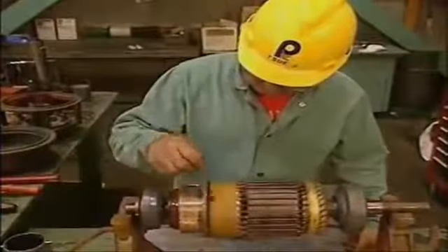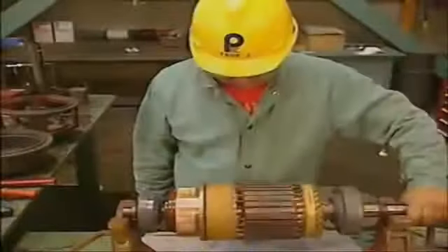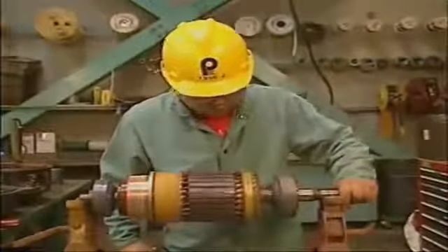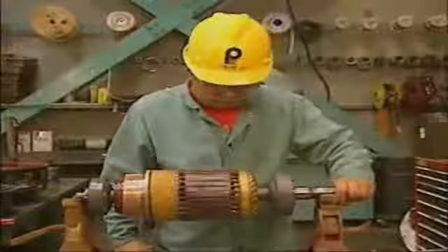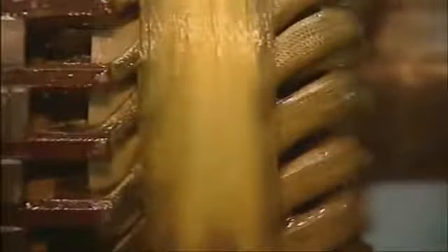The area behind the risers should be checked to make sure that there is no melted solder, dirt, or carbon dust there. If any foreign particles are found, they should be removed with an approved cleaning solvent, rags, and a vacuum as necessary. The armature banding, which is the wrappings of wire or string around the armature core, should be checked to make sure that it is tight and intact. The backs of the coils, which are the ends farthest from the commutator, should be inspected for damaged areas, and the insulation should be checked to make sure that it is not cracked, chipped, or broken.